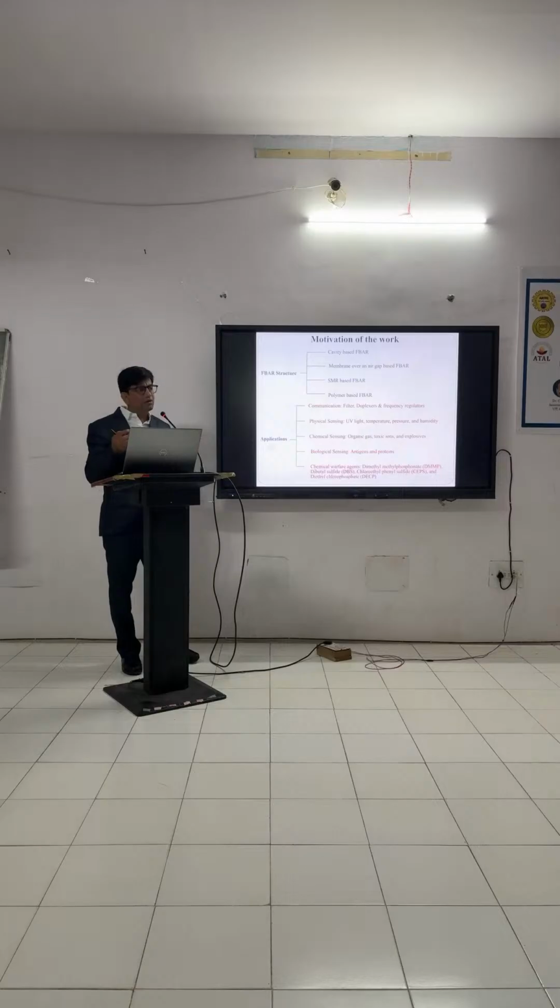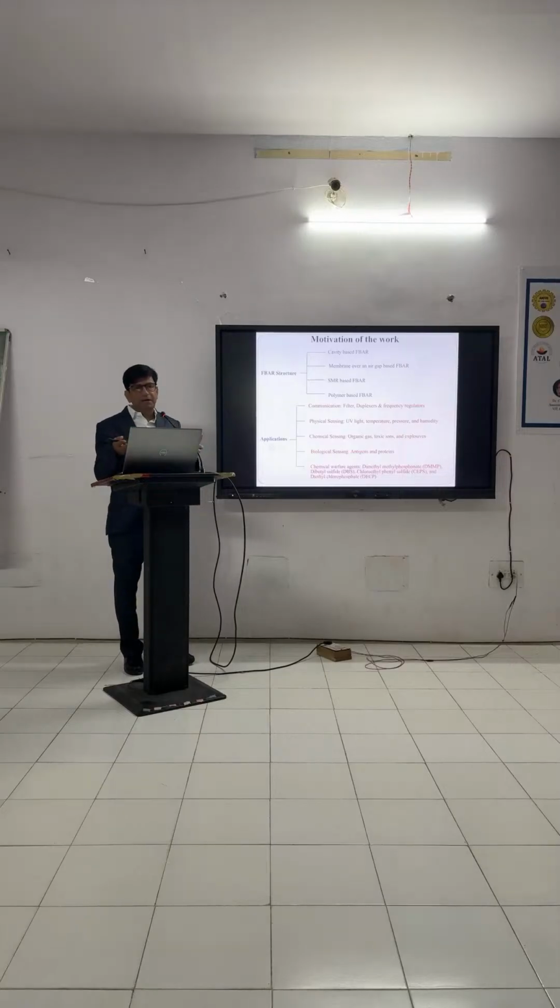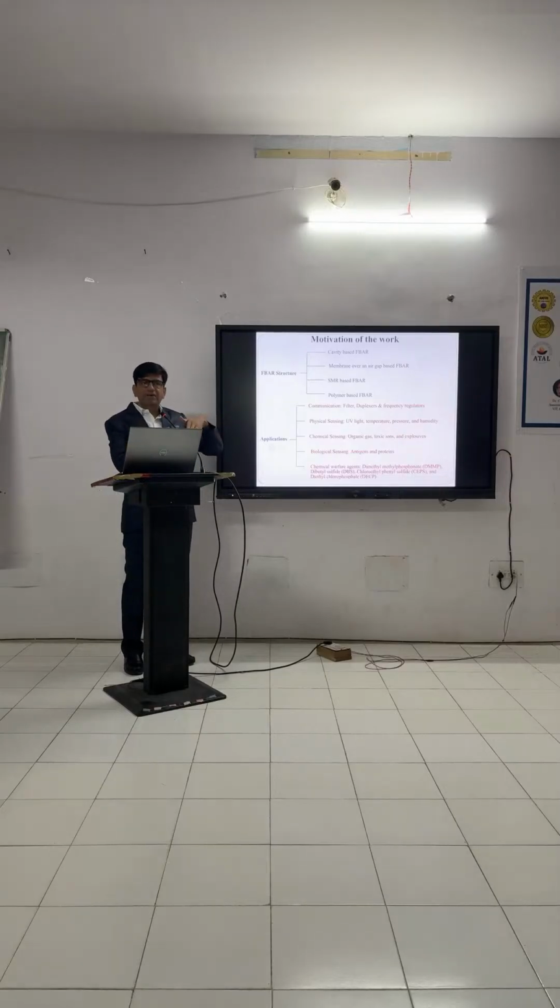And how can I confine my acoustic signal? By creating a reflector for the bottom electrode and top electrode. The top electrode I need not worry about, because on the top side I have air. I am worried about the bottom side. For the bottom side, how can I achieve confinement? We have three methods. Either we use an air cavity for confinement of the acoustic signal, or I can use a mirror to reflect my signal back to the piezoelectric layer, or I can use a polymer as a reflector to reflect my signal back to the piezoelectric layer.